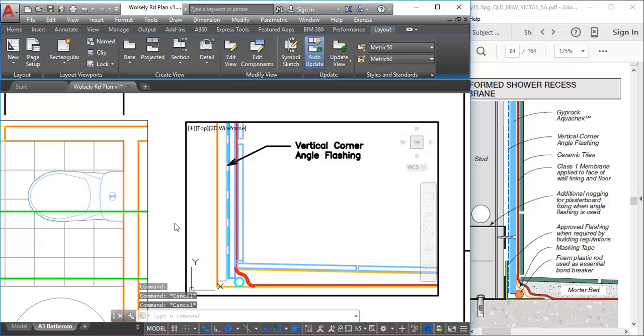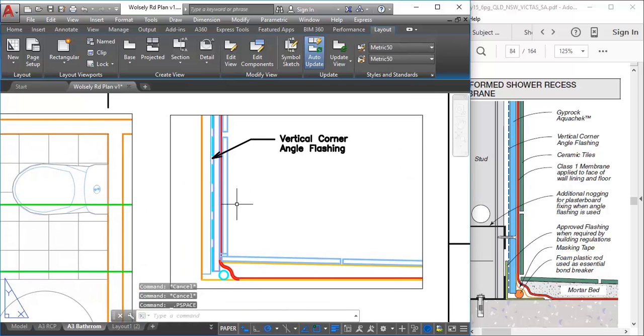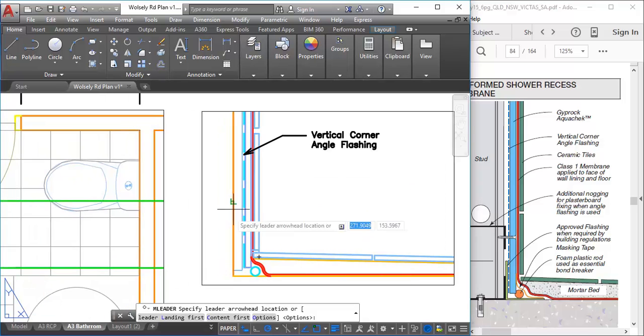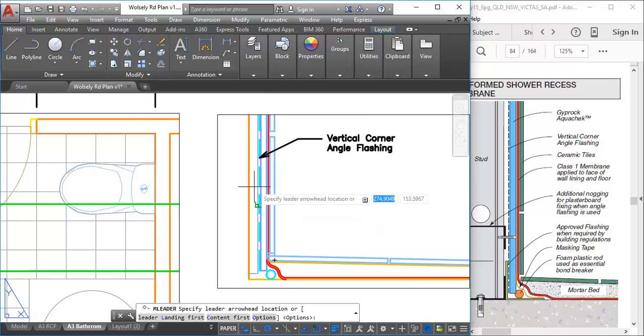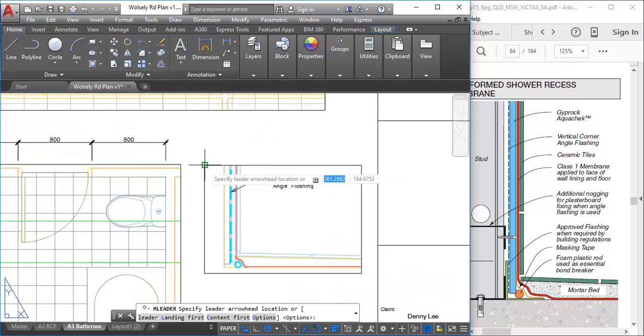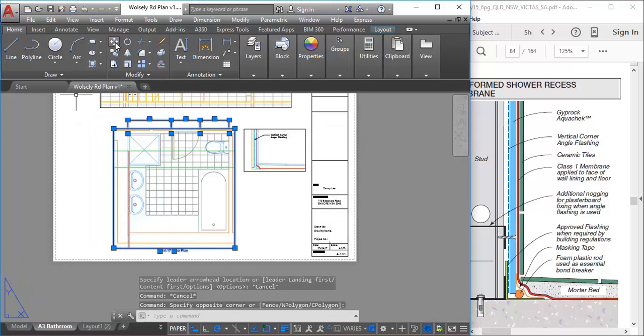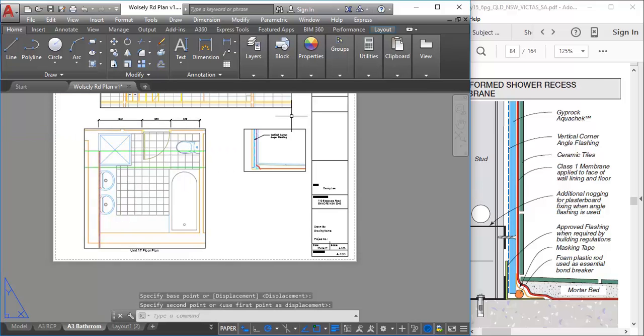So that's right. And so now all I wanted to show you is that I can draw text in paper space. So I've double clicked onto the page to go back to paper space, and you can see that down here. And if I go back to the annotate panel and go to make a new leader, so we'll do one that maybe should go outside, maybe the note for the aqua check, which is this layer here. I want that to go over to the left, and so I might actually just move these things across a little bit, so I've got some room.